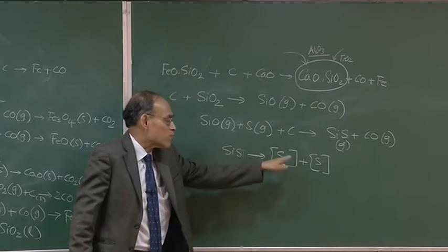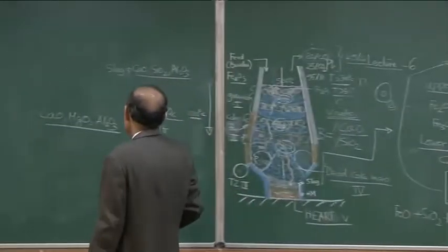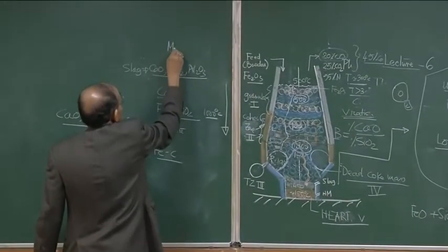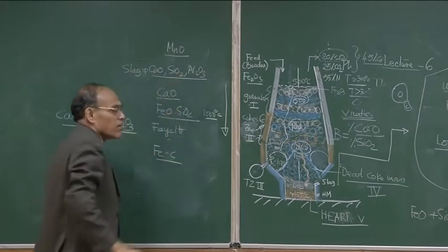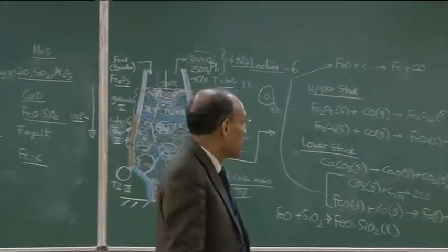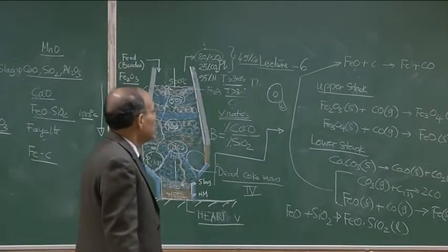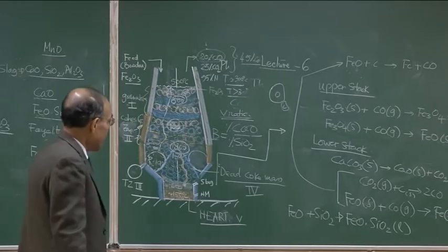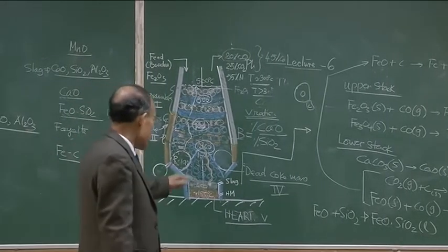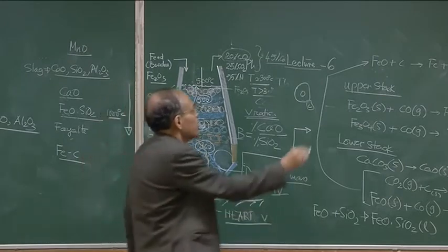So, silicon gets transferred into the metal, sulfur gets transferred into the metal. In the iron ore, we also have an important constituent, which is manganese. Iron and manganese in the periodic table are very close, they are like brothers. So, what happens to iron also more or less happens to MnO. So, the blast furnace slag virtually will not contain any FeO or MnO.